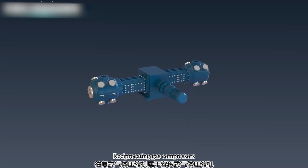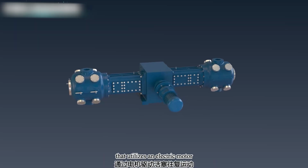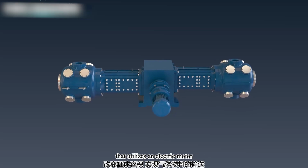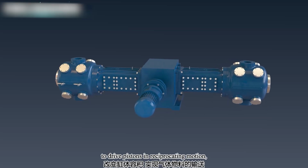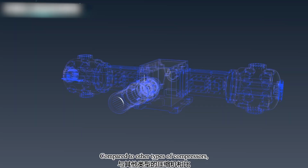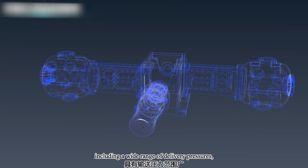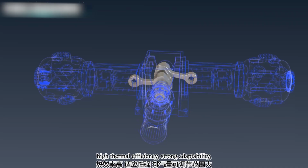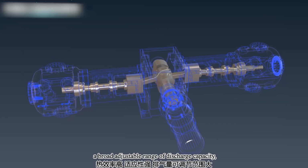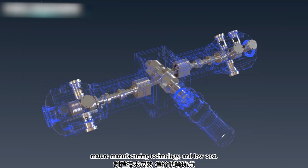Reciprocating gas compressors are a type of positive displacement compressor that utilizes an electric motor to drive pistons in reciprocating motion. Compared to other types of compressors, they offer several advantages, including a wide range of delivery pressures, high thermal efficiency, strong adaptability, a broad adjustable range of discharge capacity, mature manufacturing technology, and low cost.